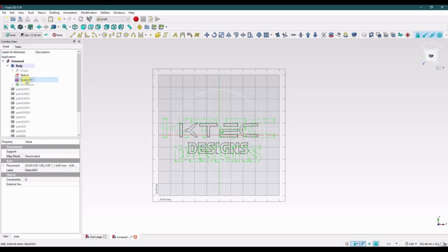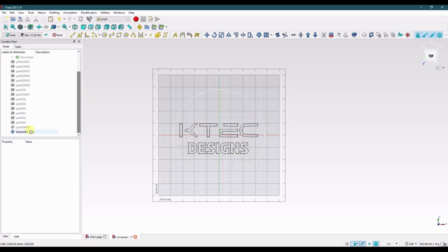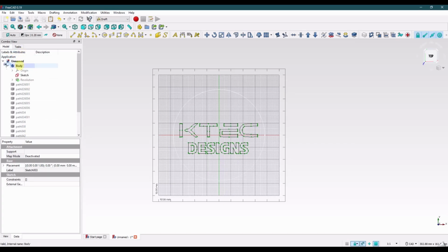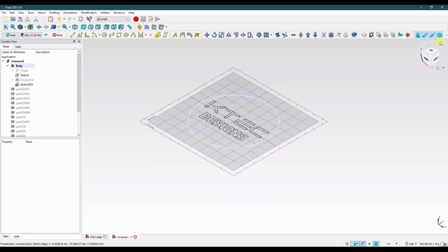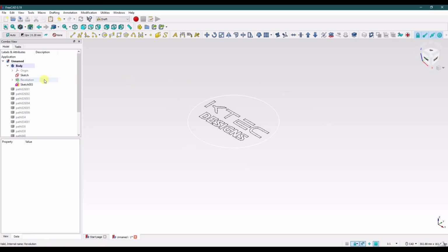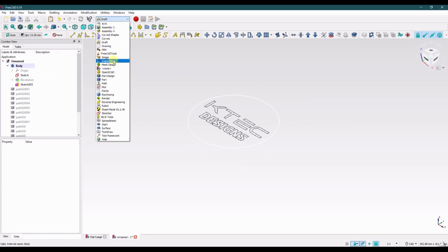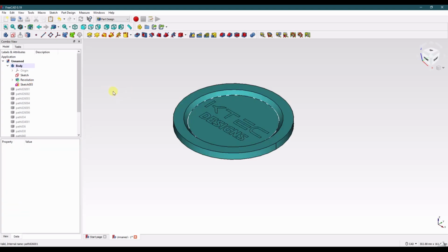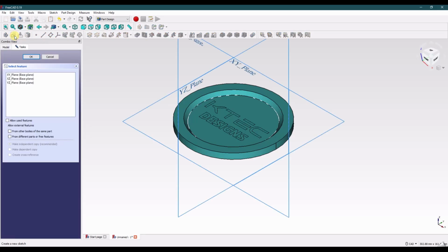Well, I guess I'm going to delete that sketch then. Take this sketch, convert it. We'll drag it up. Plop it in there. This needs to go away again. And we can go back to our part workbench. Okay. There we go. Now let's add in our little line between these two.